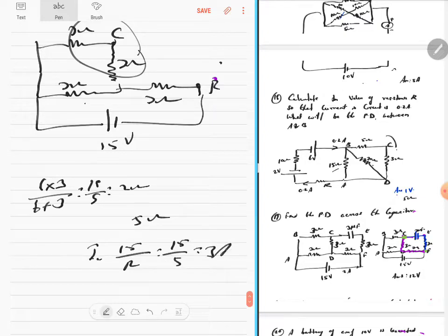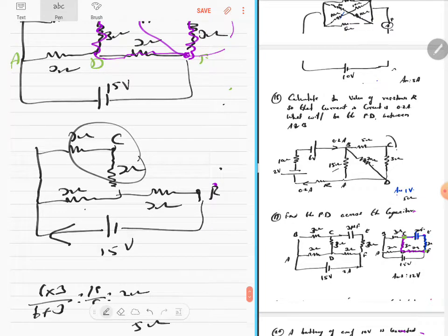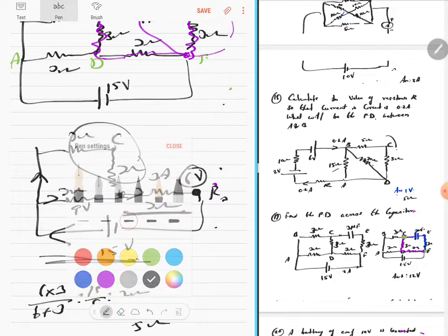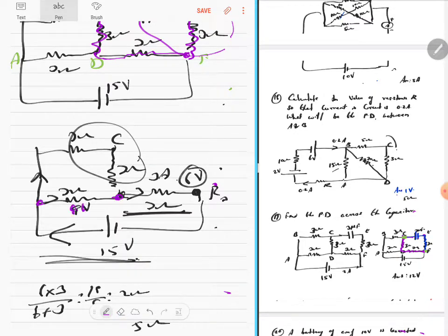You know 3 amps is the current that is flowing through here. It will get split variously across this, but when it comes here it will still be 3 amps. But this 3 amps and this 3 ohms, when you multiply IR, you get the potential across this point and this point, which itself is 6 volts. So you know the potential across this is 6 volts, the total is 15 volts. So 15 minus 6 will leave you behind with this as 9 volts. Therefore, you know the potential difference across this and this itself is 9 volts whenever they come like this or come like that. Correct? And you know this is 9 volts and a 3 ohms, you can divide and get the value of current. You know I is equal to V by R, therefore the 9 by 3 is 3 amps is the current that is flowing through here.